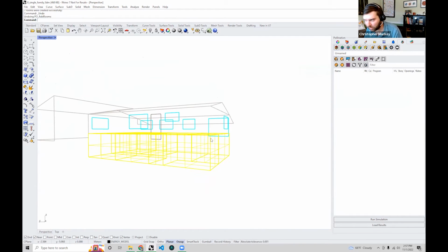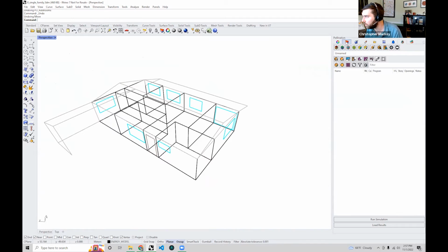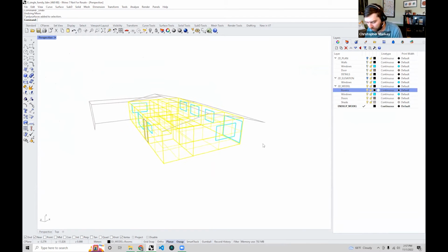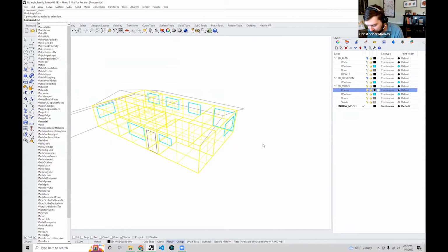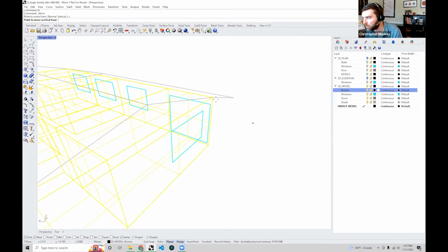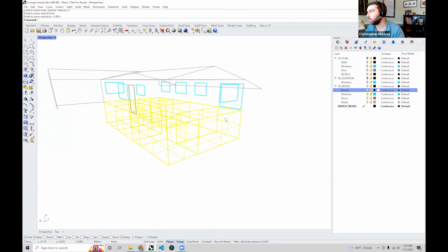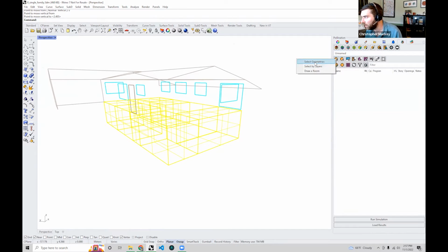I guess we have to make sure that they're completely below the Rhino origin to do this. I'm mostly just making sure that you're aware that it's not magic. If you end up with a case where these boundary conditions are not what you'd expected, you may need to move things around in relation to the Rhino origin or post-process them to reset the boundary conditions, which I can show you in a second.